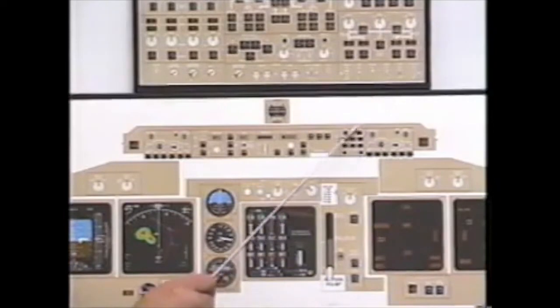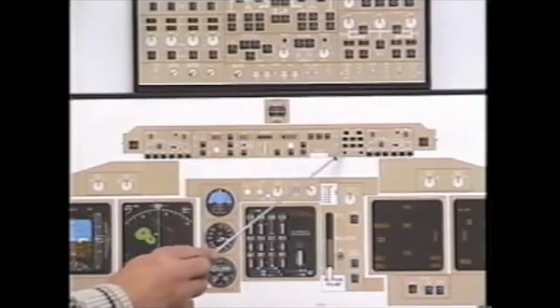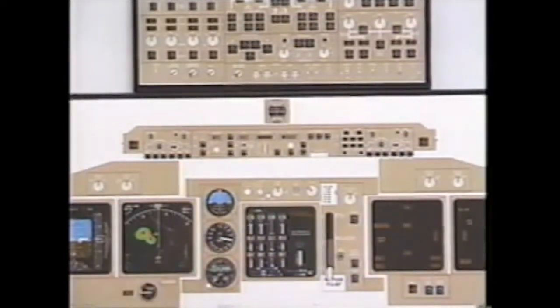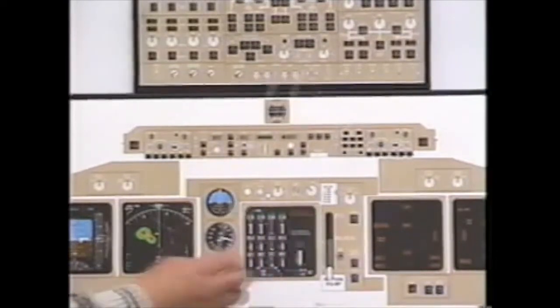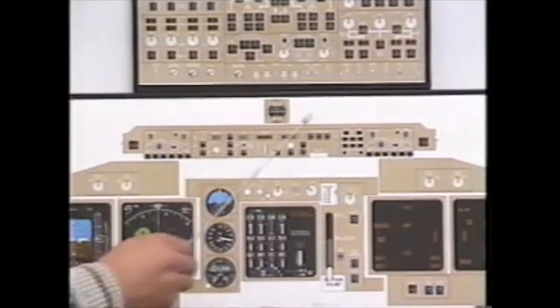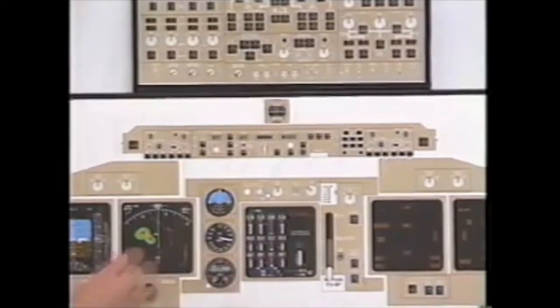ICAS control panel: the recall and cancel buttons allow you to recall and cancel the ICAS messages on the primary: warnings, cautions, advisories, and memos. Please remember you can cancel only the amber messages, thus the caution and advisory. You cannot cancel warnings and memos. All other buttons allow you to choose the synoptics for the lower ICAS. If your ICAS control panel was to fail, again, you could go to the menu page of your CDU, line select two right, and control the ICAS through the CDU.